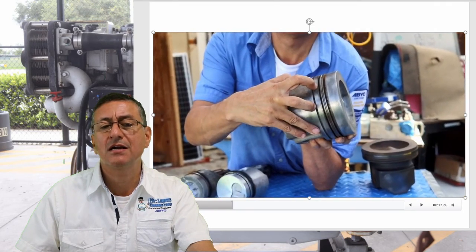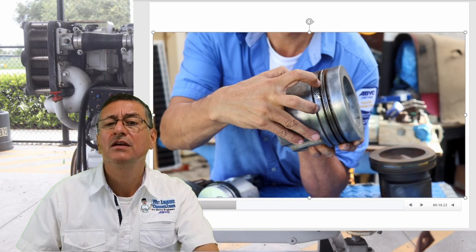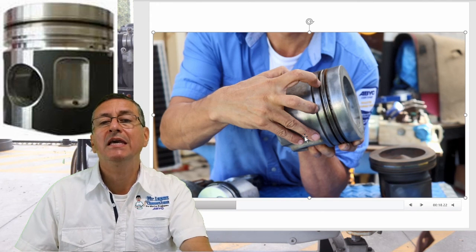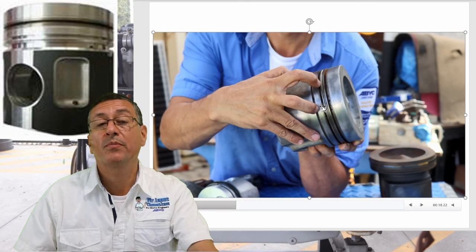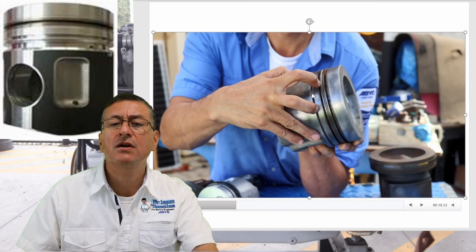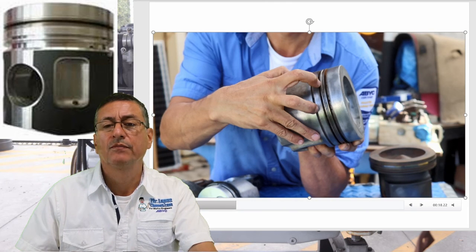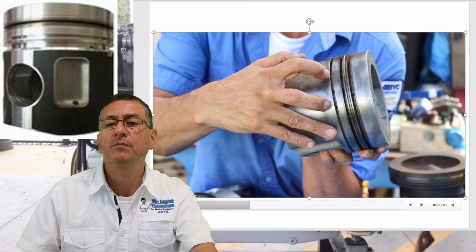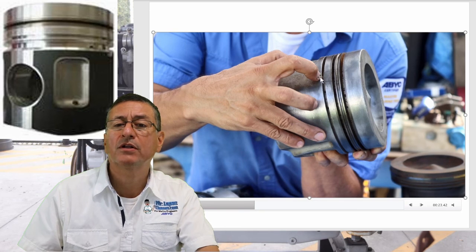Those are the inserts. Those are the inserts in steel used to protect the piston rings and used to dissipate heat. Remember that the first and the second grooves are for compression piston rings, and the third one is the oil controller. Yeah, those are the inserts in steel to protect the piston rings, and this is the bottom. This is the number 3 oil controller.